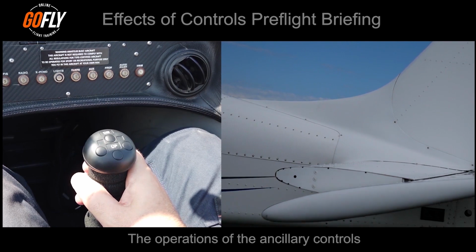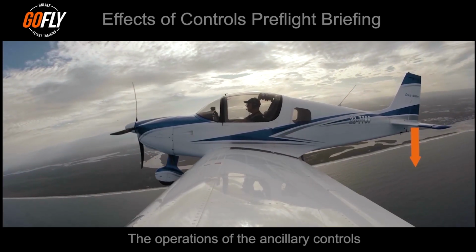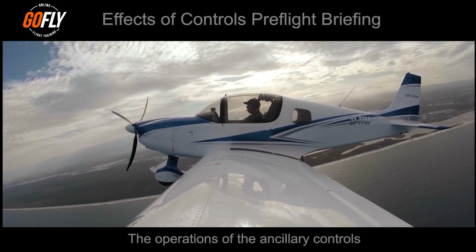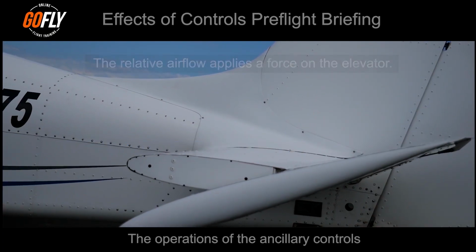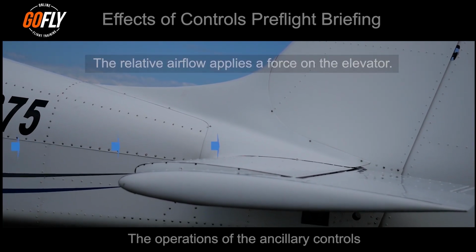Let's assume we are flying, we have moved the control column rearward. This deflects the elevator up and produces more downward force or lift to pitch the aircraft nose up. The relative airflow striking the elevator will also want to force the elevator to return to the neutral position.